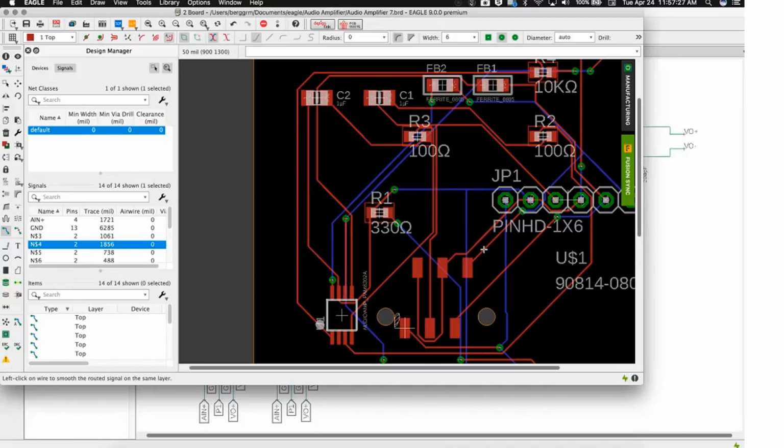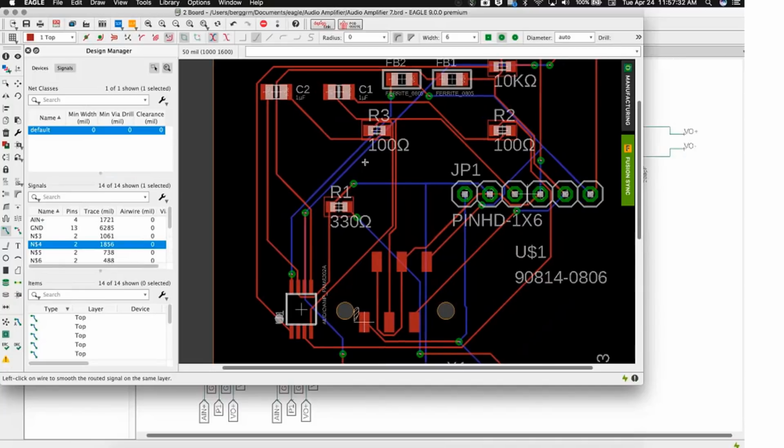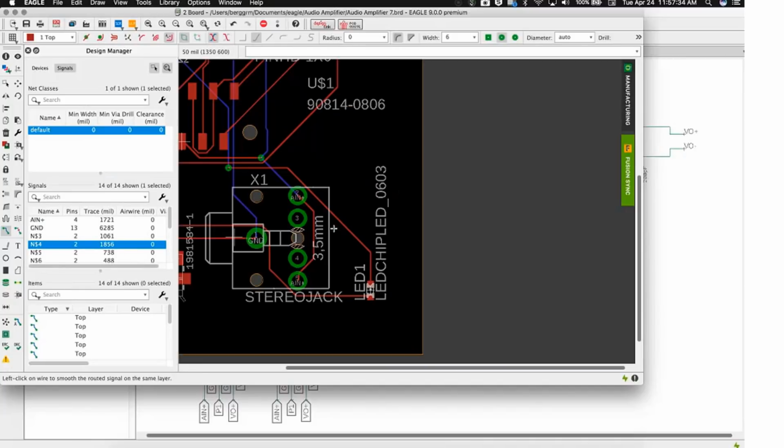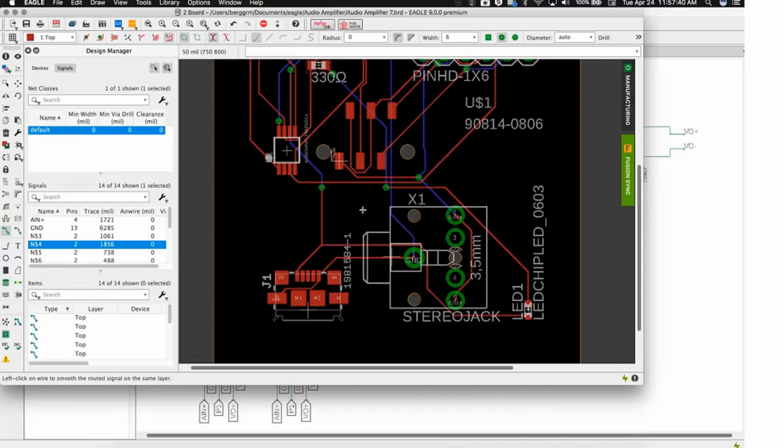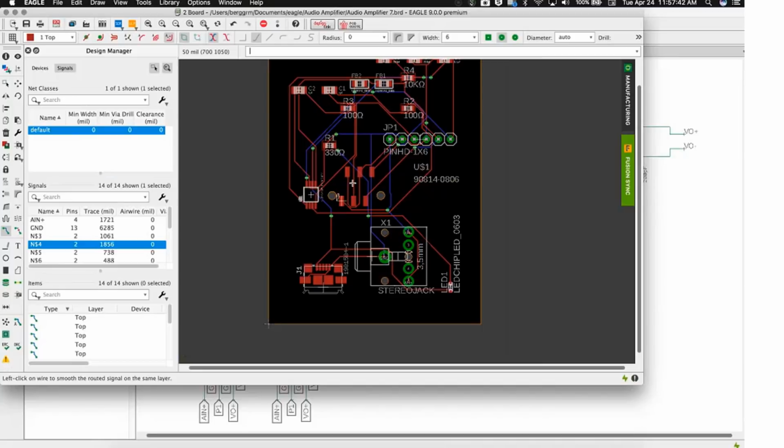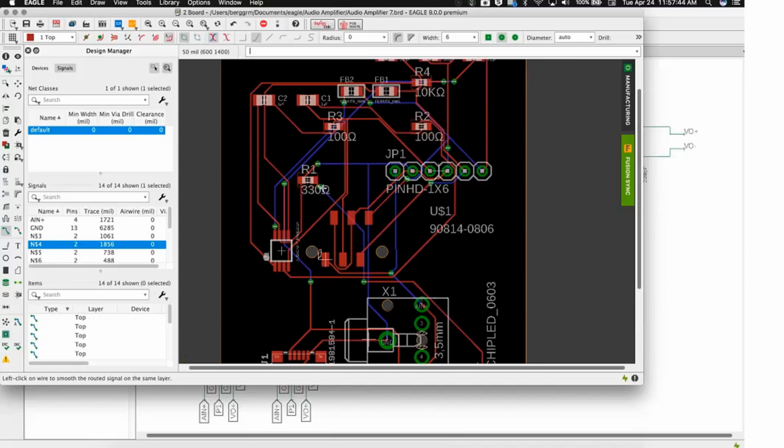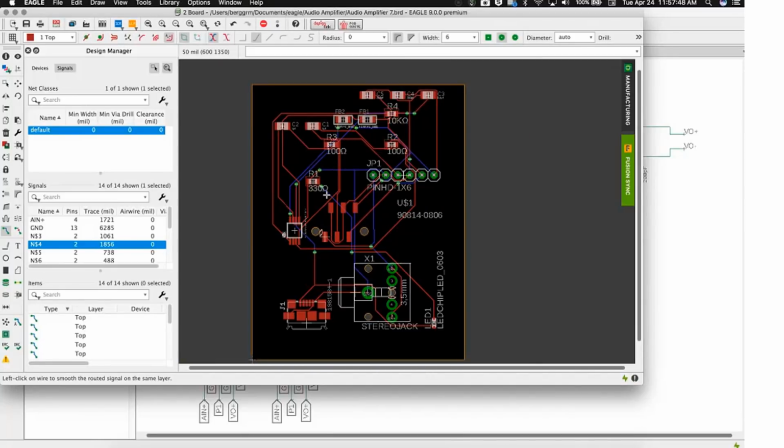Okay, yeah. So this is from Heisem. During the quick route, I see that when you hit enter, it defaults back to the minimum segment size. How can we keep the width of the trace the same? That's something that we'll definitely log and get sorted out, where we can follow with whatever the current width of the track is. We have here in the schematic, do the pins have to be on grid to be labeled automatically? No, it doesn't matter really what grid they're on right now. Yeah, correct.